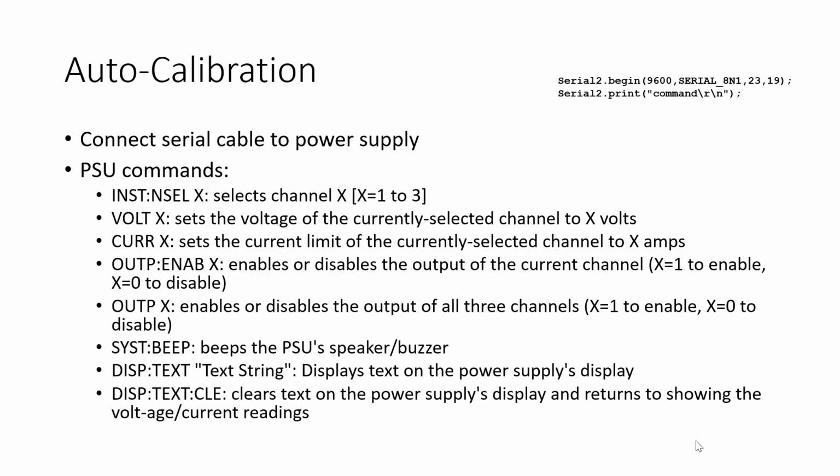So before you connect your board to the power supply, turn it on and make sure the voltages are all set to 0. The previous user could have set them to anything, like 30 volts, and we can't tolerate anything over like 14 volts. This one's 0. Mine was set to 16 volts when I first turned it on here. So just make sure of that before you plug in your board.